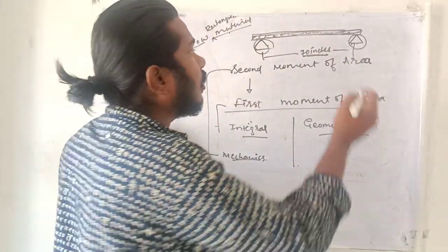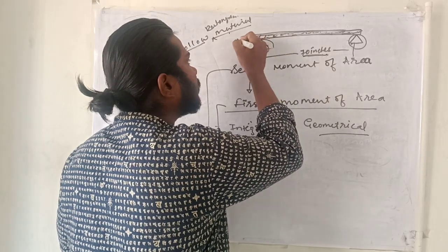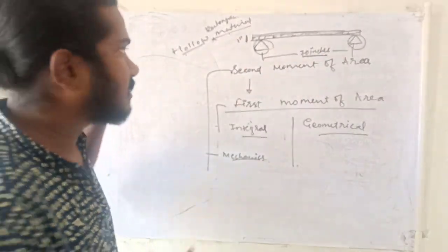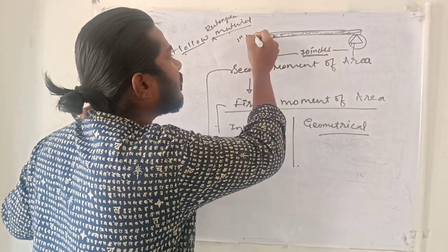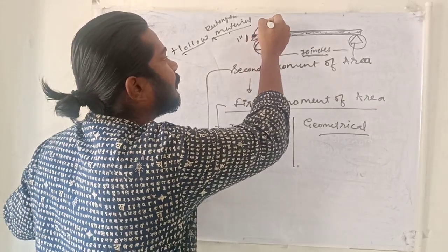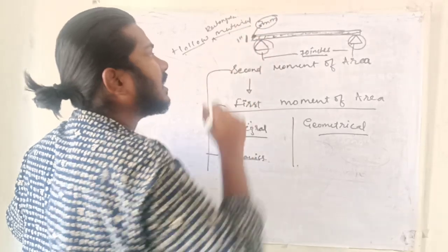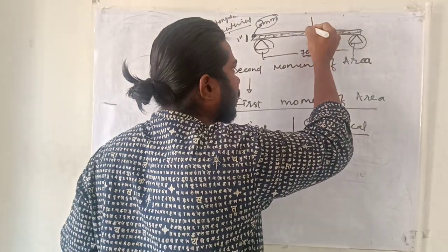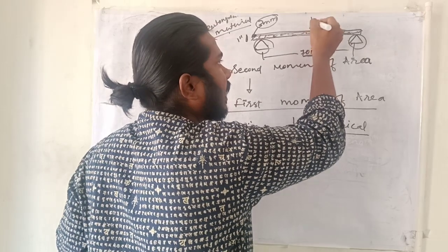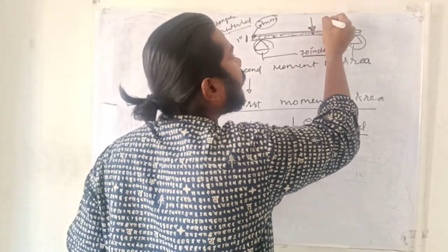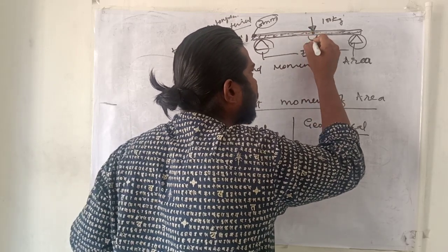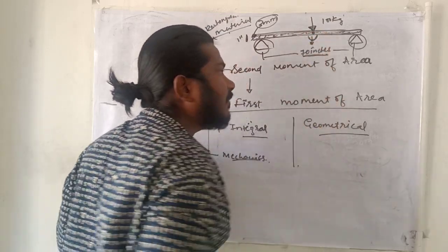For the cross section, take it to be 1 inch, and the length, as you already know, is 70 inches. Take the thickness to be 3 mm. If I apply, exactly at the centroidal location in the middle, a load of 100 kg, you can witness some deflection in here.